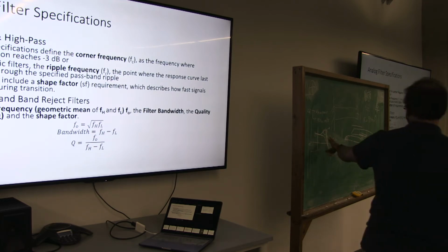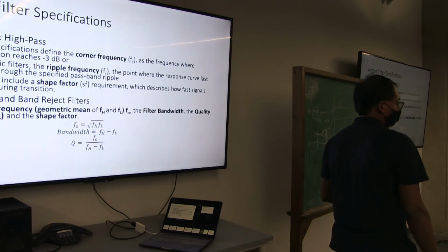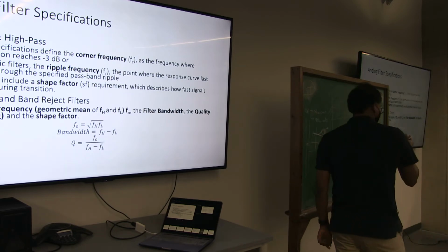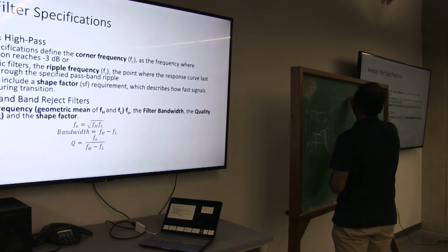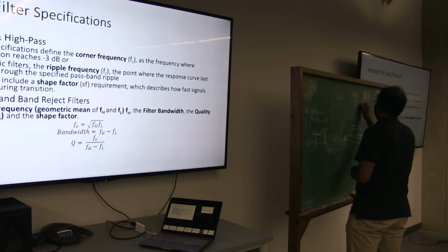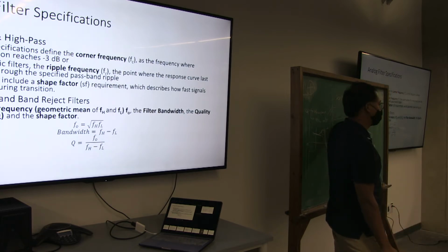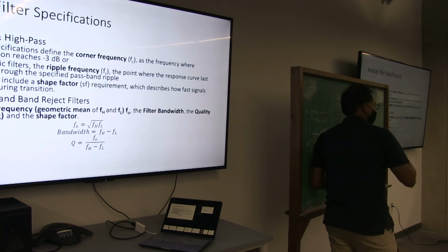Yes, they also have a quality factor. But is it dependent? It's not dependent on FH, FL, right? Those aren't defined. Right. So a generic denominator of a transfer function of any second order low pass filter can be written as this denominator of S. So this is the generic denominator for any second order filter. So this quality factor is what determines the peaking.